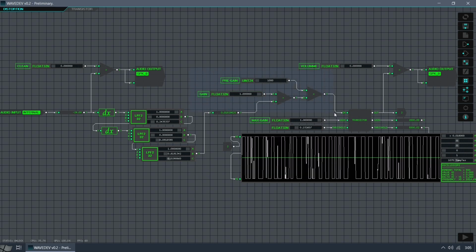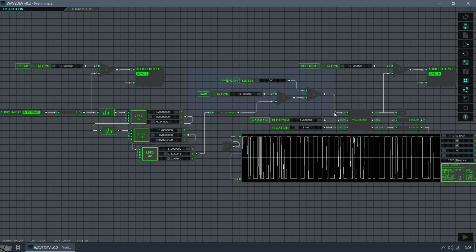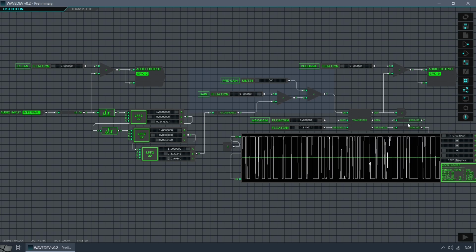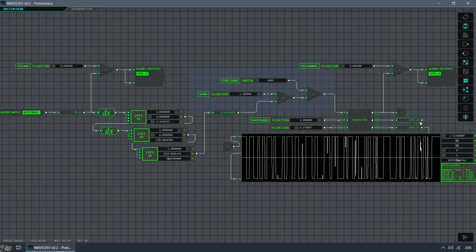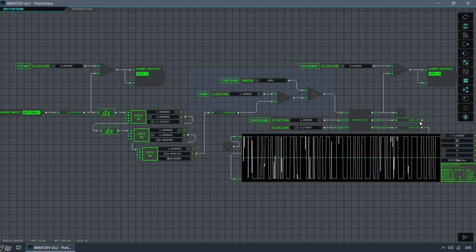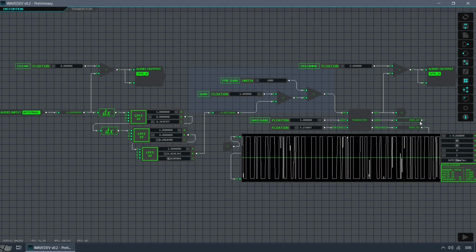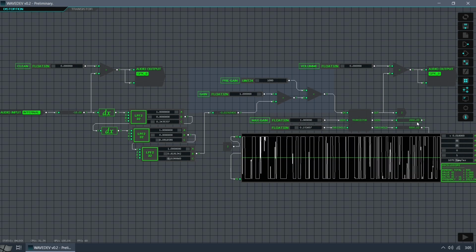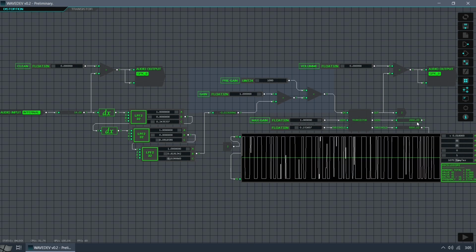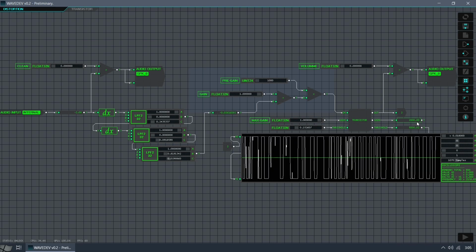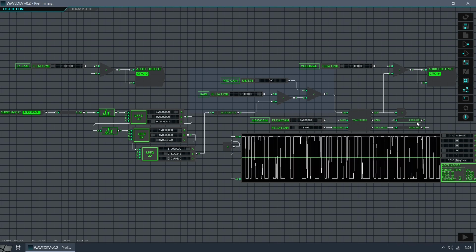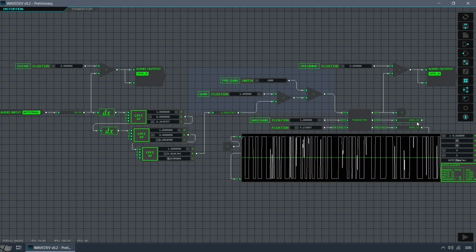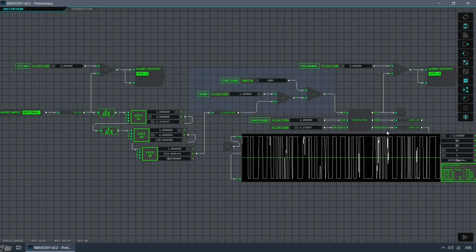Now, this add-on is optional. I make this adjustment to forget about the gain control. This value can be 1000, as well as 3000, and that's fine. Precision is not critical here. What is important here is that a gain of 2000 is a more realistic value, and it is equivalent to infinite gain. So you don't need to search for anything above this limit, since it will not contribute more harmonic content to your effect. On the contrary, you will only harm your sound by benefiting the noise.